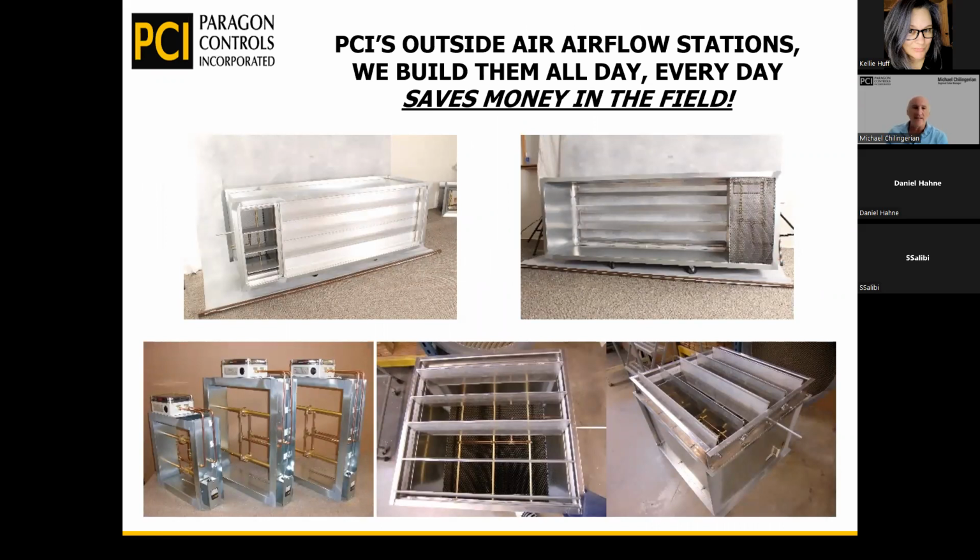At Paragon, we do a lot of different things to make a damper and airflow measurement system work together correctly. In a lot of cases, on the top left-hand corner, this is a min OA and a mod OA, and they just happen to have the airflow measurement on the min OA, so they can prove that they're bringing in outside air. The smaller ones on the bottom left-hand corner just show some small outside airflow measurement systems. These were fully set up with the damper, the transducer and the temperature sensor all together.